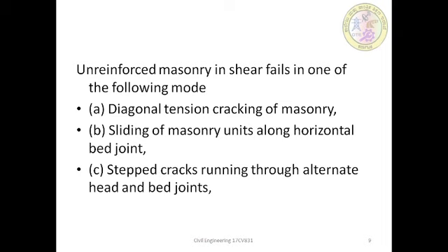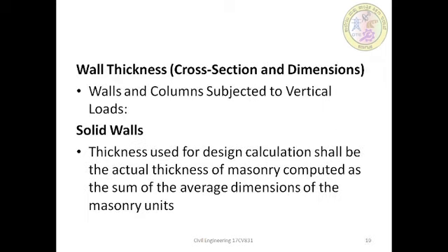The coefficient of friction of 0.2 has been used in the masonry codes. However, recent research indicates that higher values, that is 0.45 or so, are more appropriate, and at larger pre-compression, that is greater than 2 MPa, tensile cracking of masonry is more likely, which is expressed in terms of the square root of the compressive strength of the masonry.